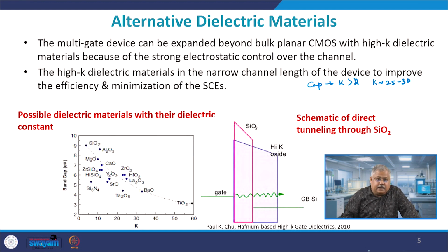And therefore, an appropriate K value means that the dielectric will have a large physical thickness, which will prevent the gate leakage, and therefore I off will be reduced, and it is also not too thick to hamper physical scaling. So, that is where the challenge is, at least for the dielectric: it should not be thin enough to induce tunneling, and it should not be thick enough to sort of be an impediment in scaling the device.